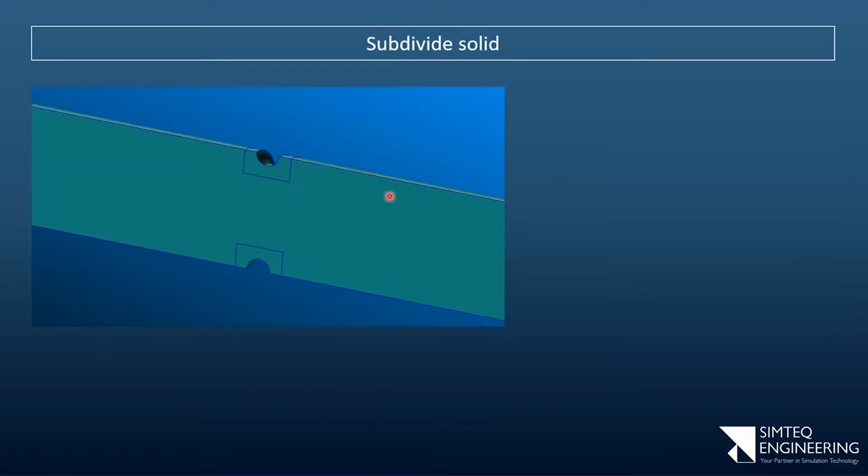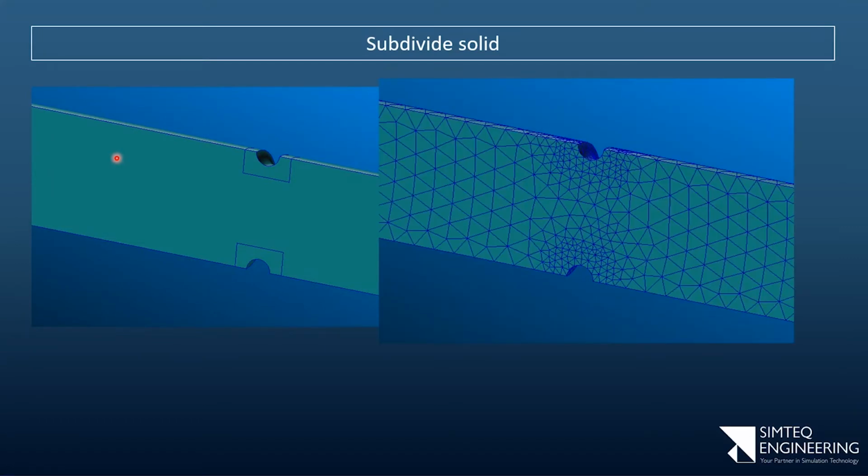That gets us to subdividing a solid. So if I take a disk that I cut out there, in this case, I can make that section a lot finer. And the solid on this side, the remaining solid, I can then mesh a lot coarser again. So if I look at that, it's not that clear, because that edge you can still see nicely, but the one going up is a bit harder to visualize. But it's exactly from this model that this one was created. So in this case, this whole section was meshed with finer elements.